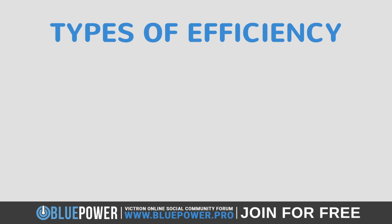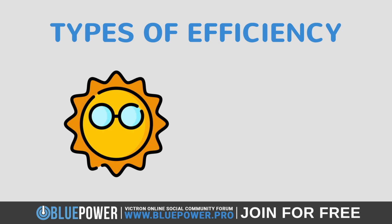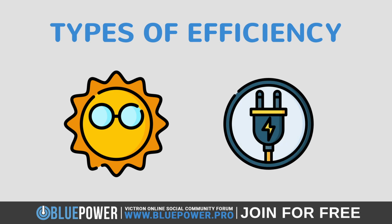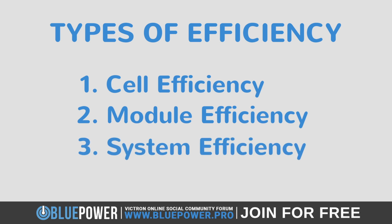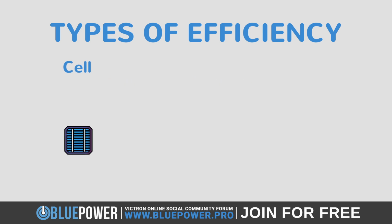Solar efficiency can be understood at various levels, each reflecting different aspects of how effectively sunlight is converted into electrical energy. These types include cell efficiency, module efficiency, and system efficiency. Cell efficiency is a key metric used to gauge the performance of individual solar cells under standard test conditions. The efficiency of a single solar cell is typically higher than module efficiency because it does not account for losses in wiring, shading, and other real-world factors.